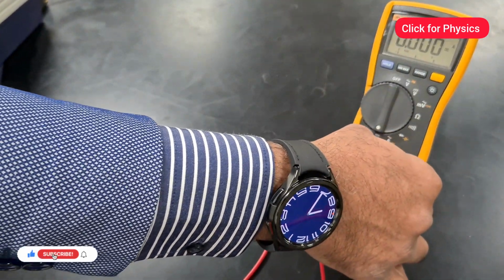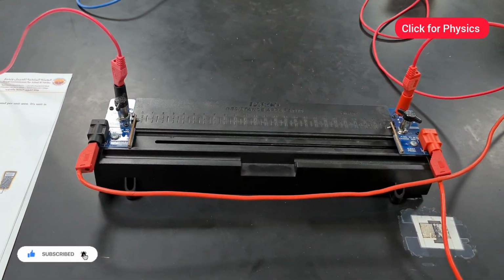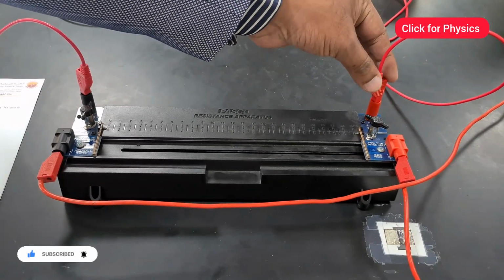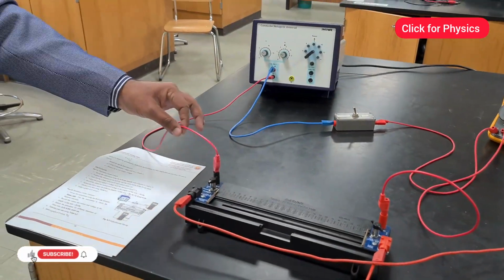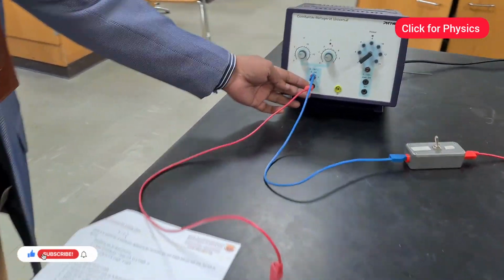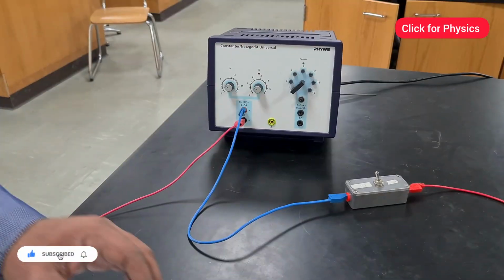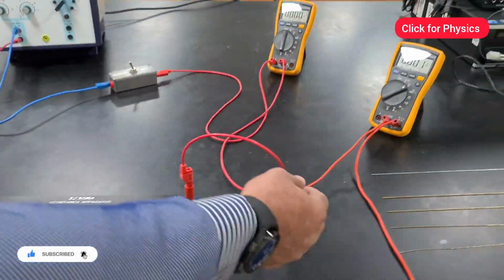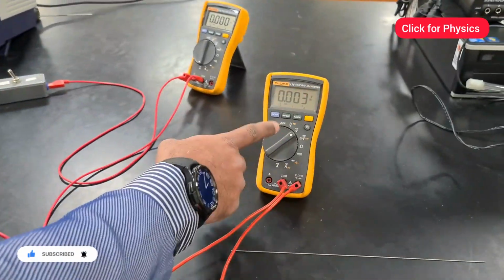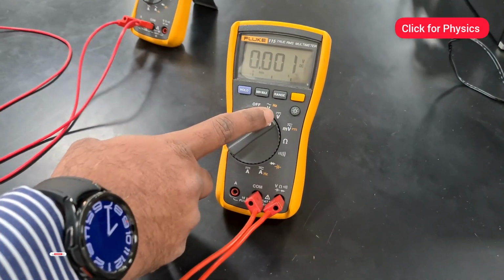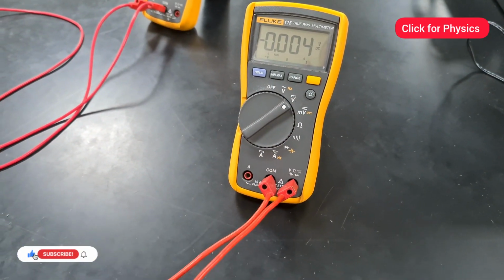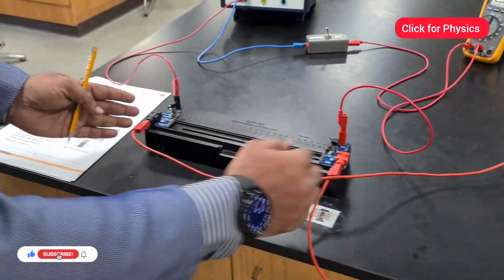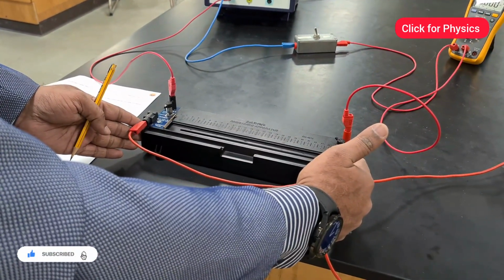Then from the other end of the multimeter, we gave the connection to the resistance apparatus. You can see the connection for one end is given here, and from the other end of the resistance apparatus, we connected back to the negative terminal of the battery. Clear? Now we are going to use another multimeter for measuring the voltage. You can see this pointer is indicating the voltage. We are going to connect this voltmeter exactly parallel to the resistance apparatus.